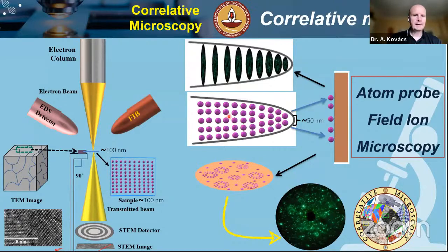Indeed. Pradeep, I have a question actually. Because we went through half of the periodic table basically, what are the elements that can be detected, but how about the very, very light elements? Because if we are talking about hydrogen, hydrogen is pretty much not possible to detect with transmission electron microscopy, and basically the background of that is that the electron wave does not really interact much with the hydrogen atoms or molecules. So how about the atom probe tomography reconstruction?